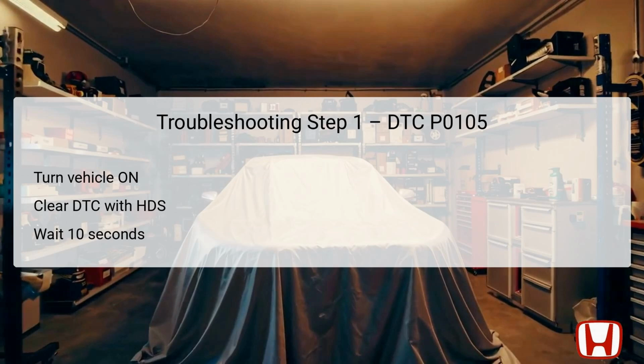readings. After clearing the DTC, wait for at least 10 seconds to allow the system to reset properly. Finally, check for any pending or confirmed DTCs once again using the HDS. If DTC P0105 is still present, it confirms that there's indeed an ongoing issue to investigate further.